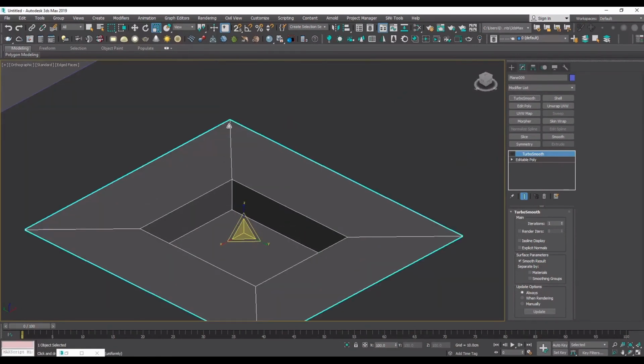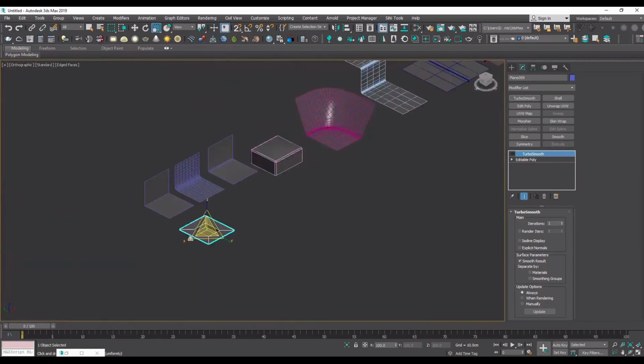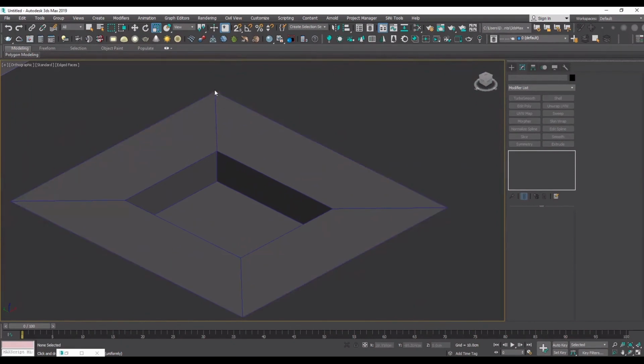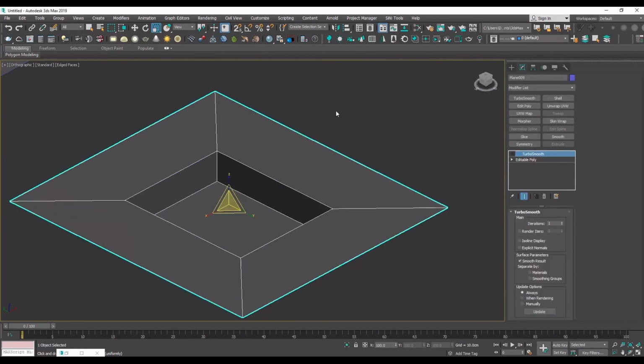These diagonal edges that connect to our inner part result in Turbo Smooth redirecting and counting it as if it's a circle shape. But as you see here, we do not have such lines and edges for Turbo Smooth to do something other than a regular edge loop. Now, not only do we have to correct the inner extrusion on the inside, but also our plane's corners on the outside. Now I enter editable poly to be able to ring select the outer edges.